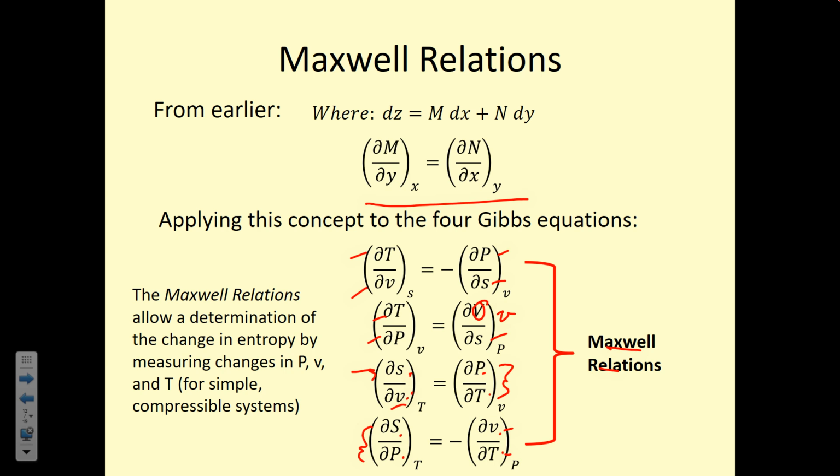When you have an isentropic efficiency, that means that you're going to have an actual enthalpy and an isentropic enthalpy, right? So you can use s to calculate your isentropic enthalpy. Well, if you have an isentropic efficiency, it means that your system is not actually isentropic, right? So entropy at state 1 is not actually equal to entropy at state 2, which means that you have to find the actual entropy in order to perform the rest of the calculations.